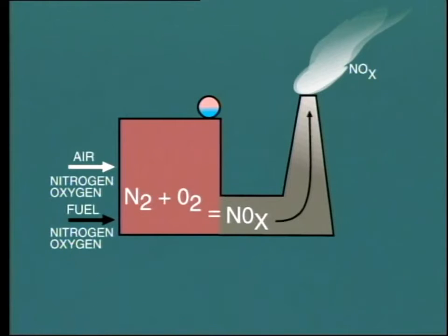NOx includes various nitrogen oxides which are formed during the combustion process by high-temperature reaction between nitrogen and free oxygen. Both of these elements are present in the combustion air, and small quantities may also be contained in the fuel. When discharged to atmosphere, NOx causes irritation to the eyes and throat and may even cause respiratory problems in certain individuals. It is also thought that NOx affects the ozone layer and also contributes to the formation of smog.